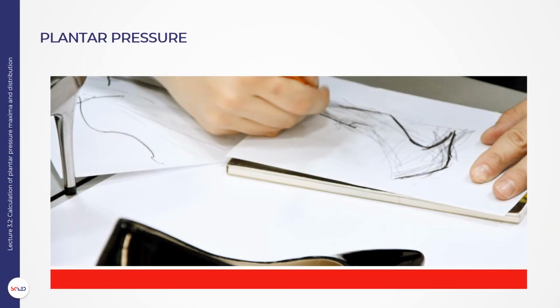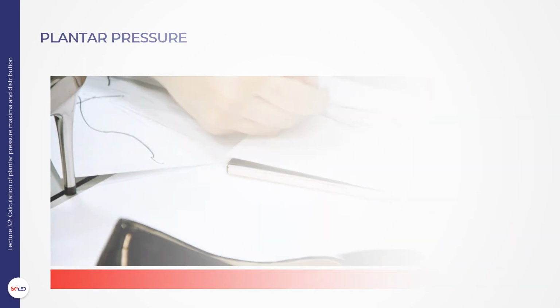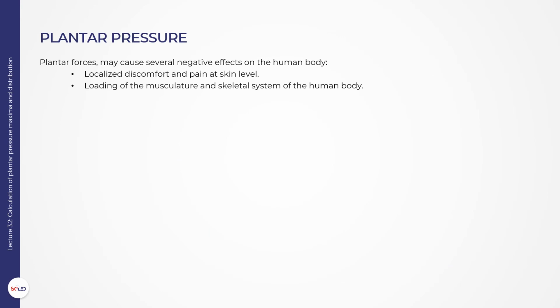Plantar pressure. Plantar pressures are caused by the ground-to-body reaction forces due to the human weight and other movement-related effects. Footwear intervenes between the plantar surface of the foot and the ground, and its geometry and mechanical properties affect force transfer characteristics. Plantar forces are analyzed into vertical, lateral and longitudinal vectors, of which the most critical are the vertical ones. These, if excessive, may cause several negative effects on the human body, like localized discomfort and pain at skin level, and loading of the musculature and skeletal system.